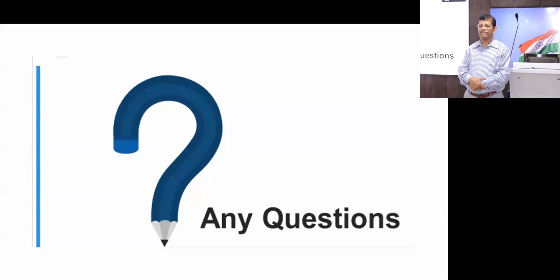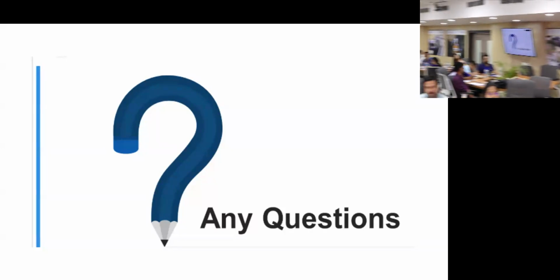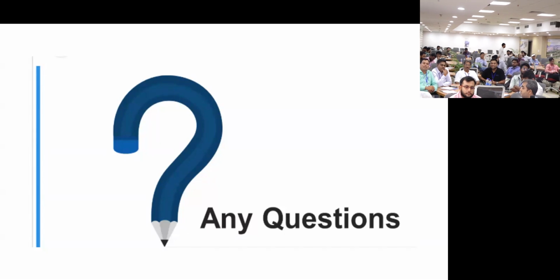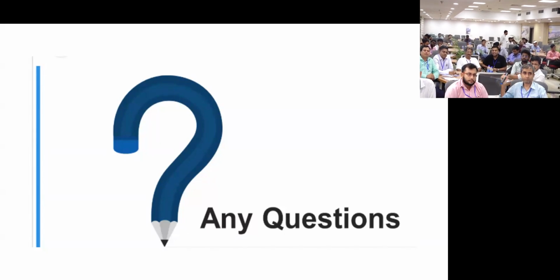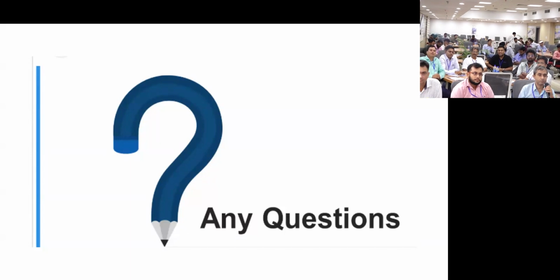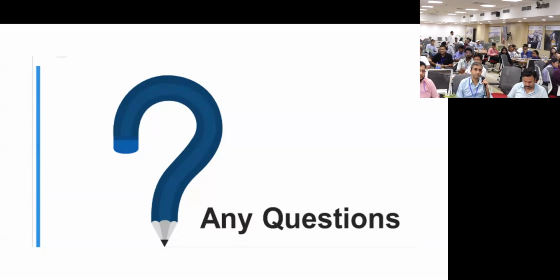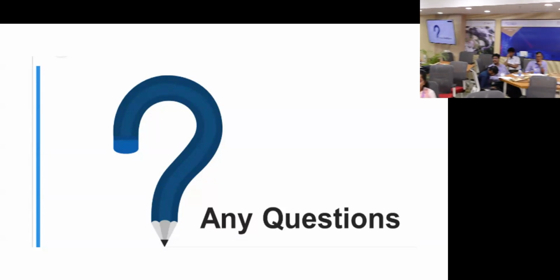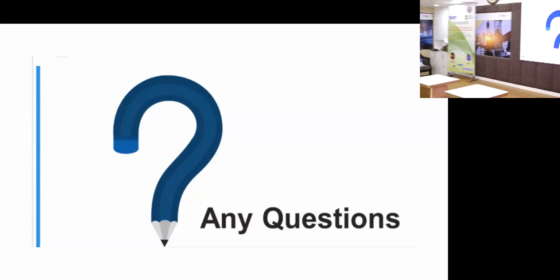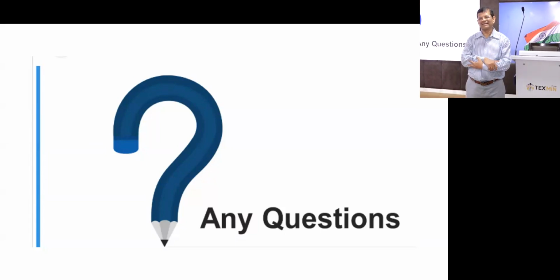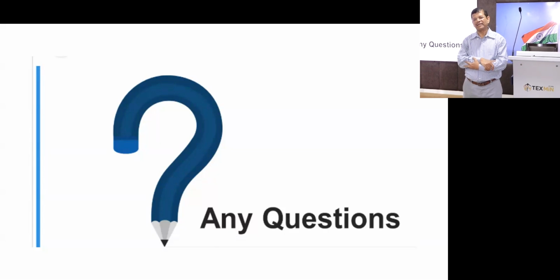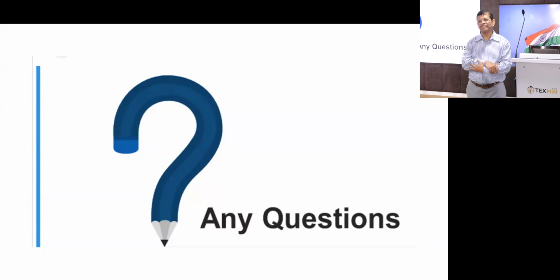Okay sir. Sir, for both tests, we have to collect the sample from the field and send it to the lab, and collect the data from the lab, no? Lab data is important, but if you have good CPT interpretation, we can get data from the CPT also, from the site. CPT is the on-site test. We can get the result at site only, during the test. But sir, the C and phi parameters we cannot get from CPT, sir.